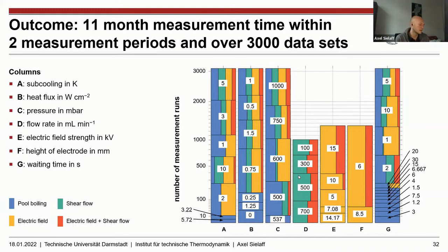So everything had to be quite tight and fixed. The heater was implemented in a press fitting, and sometimes we got the onset of nucleate boiling at over 2.5, 3 watts per square centimeter, and by that we broke the crystal by thermal stress. So we decided to reduce this requirement to 1.5, because this was secure operation.